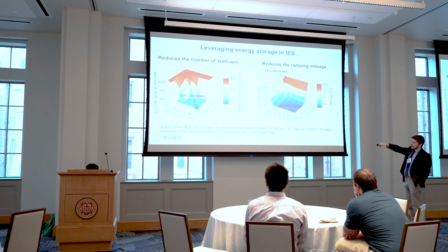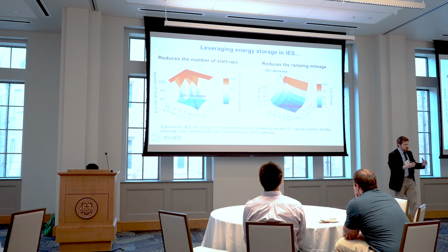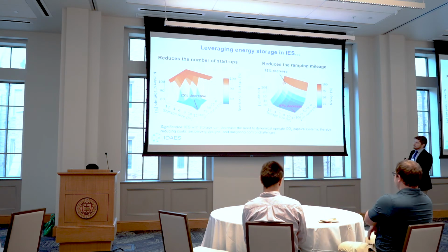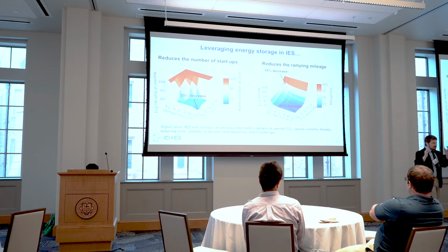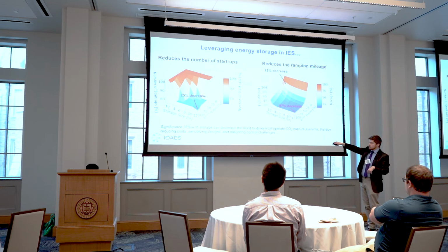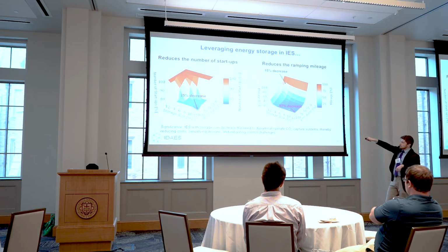system, the storage size, its maximum power relative to its storage size, and then how it changes the number of startups that this generator would need to undergo, and it changes the mileage or how much the generator would need to change. And what was really interesting in this analysis is we found the energy storage didn't help the overall economics of the system. But what it helped was reducing these numbers of startups and reducing this mileage.